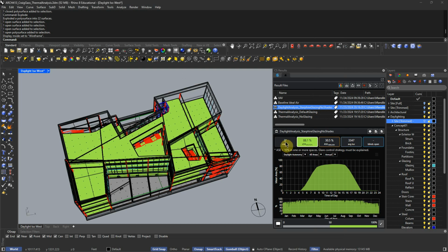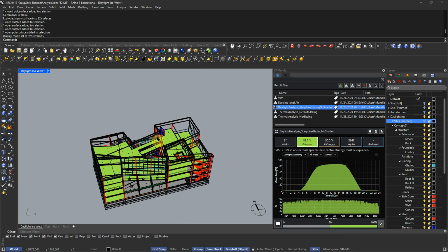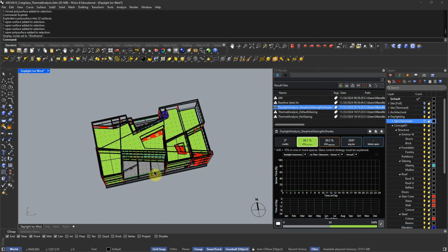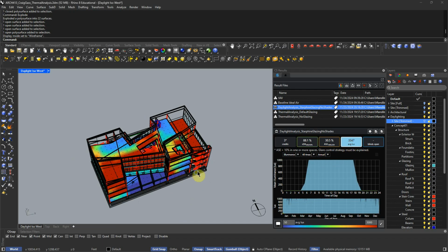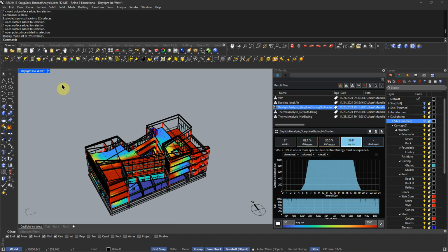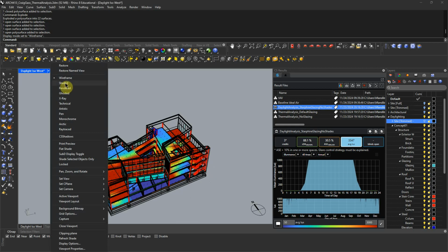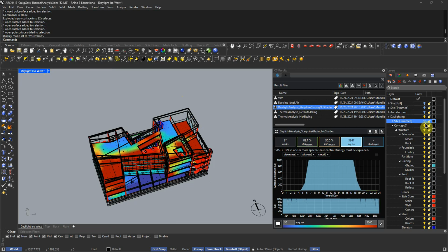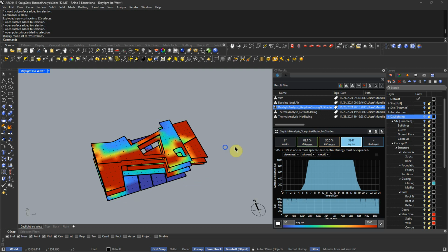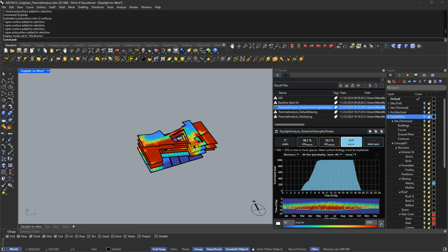Our goal is 3 credits. We get that by getting an SDA, which is, the green is, do we have enough light, of 75% for all the regularly occupied spaces. But what are regularly occupied spaces? Let me just turn off everything and have just the simulation.